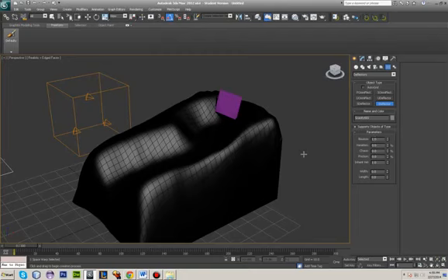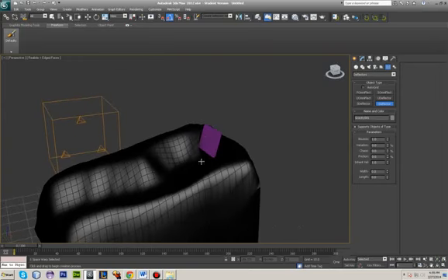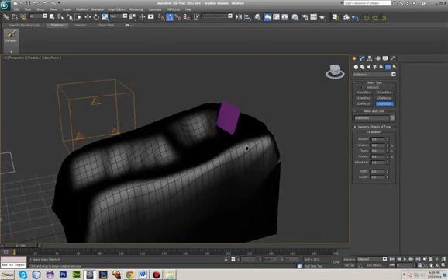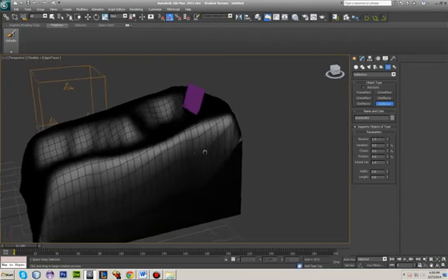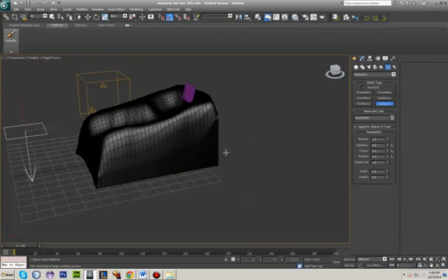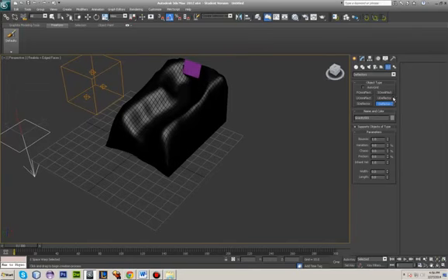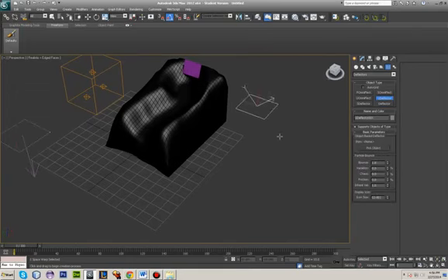The bounce is set to 1 right now. That means that if particles hit the deflector, they will actually bounce out of it. We don't want that because that's not the natural behavior of water, so we'll be changing that to 0. To do that, we're going to click on U-Deflector and just draw it out as any other